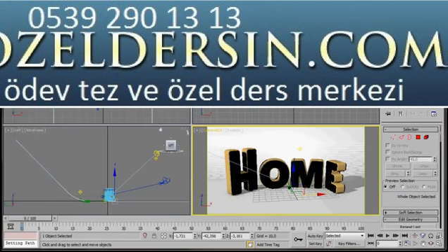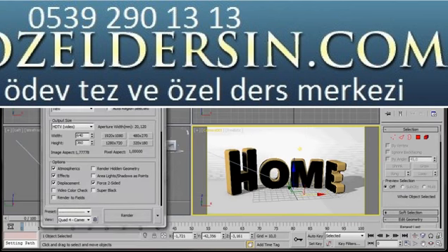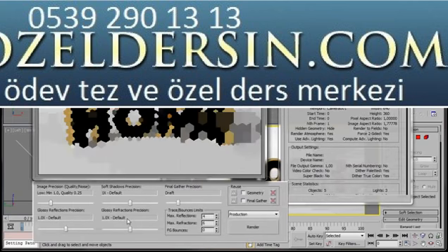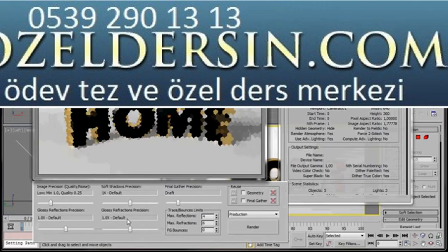Let's go to Render Setup on the main toolbar. Now here in the dialog, we're going to scroll right down to the bottom to Views, and make sure it's in Camera View, then we're going to lock it. Let's press Render. Even though we have chosen a small output size, it's going to take time to render, so I'm going to turn off this video while it's rendering.